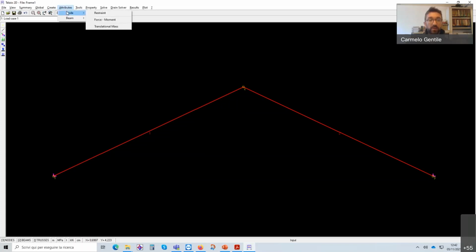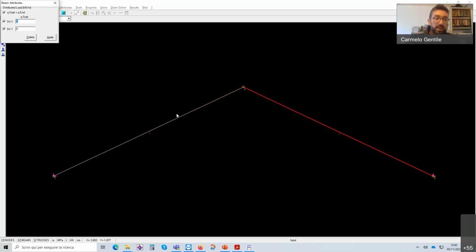Now, let's go for the load. This time the load is distributed, it's no more concentrated in 1 point. So, you just follow my flow, okay? And try to be critical about it. In this case, the load is an attribute to the beam, not to the node. Distributed load, we select element 1, and we have that the vertical load was -3 kN/meter in the y direction. Apply. Okay, this is what we expected.